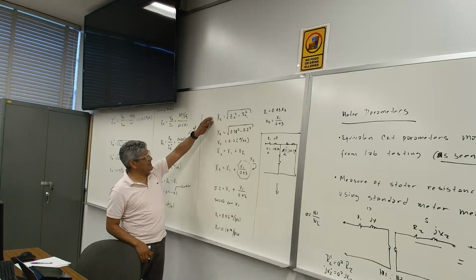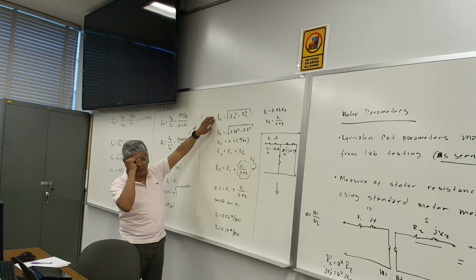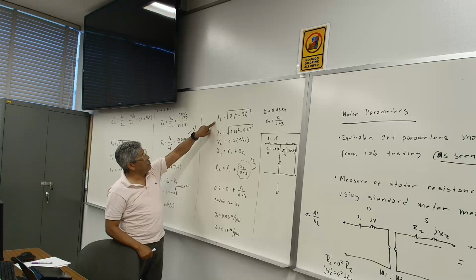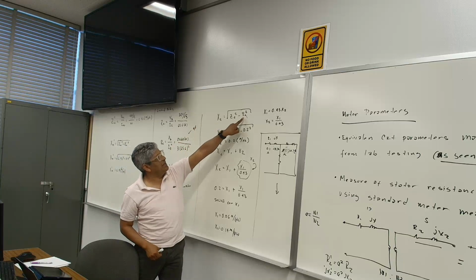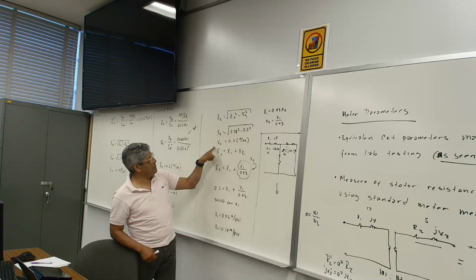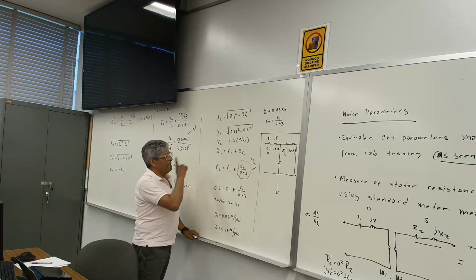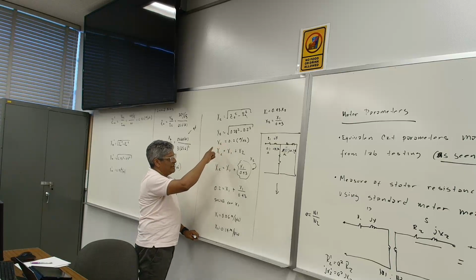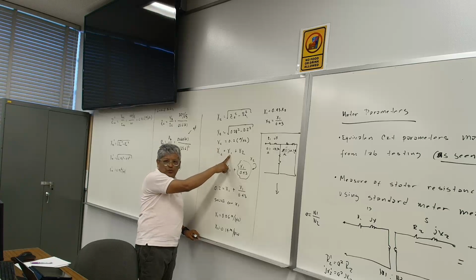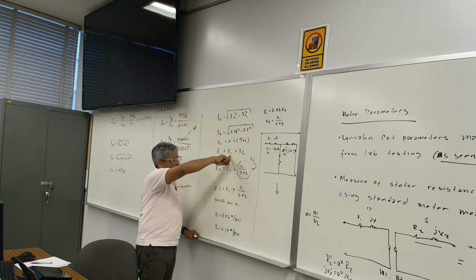Now the reactance. First we got the total reactance of the machine, which is the combination of the reactance of the stator and the rotor. On that one, we know XE, we've had this value already, so we compute XE, which is the total combination. I know the value of XE, and I'm after X1. So I need to solve for X1.